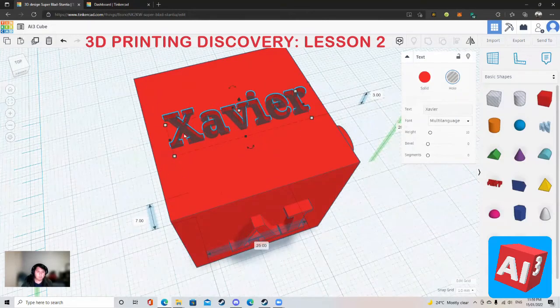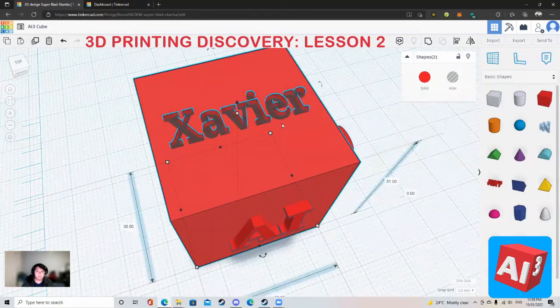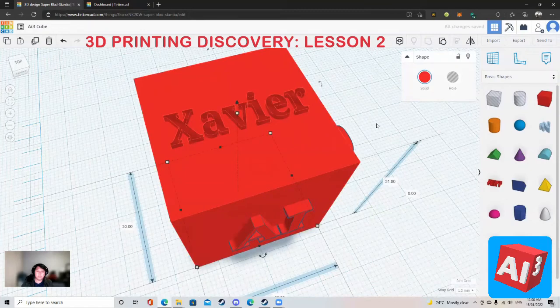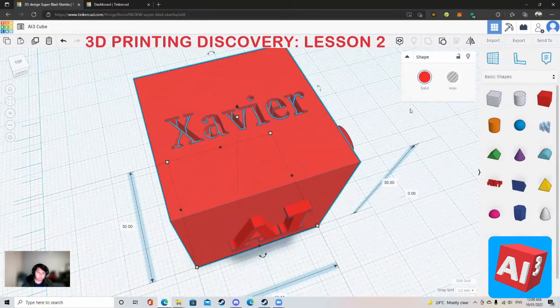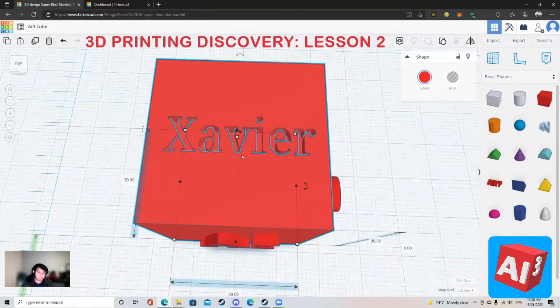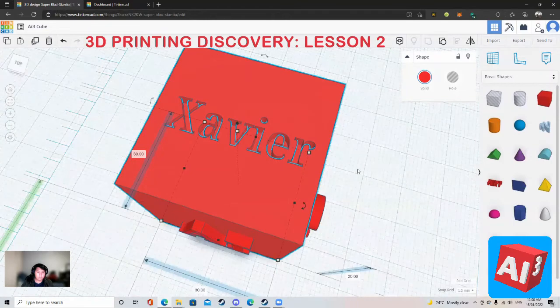So what I'm going to do is, while selecting this, I'm going to press Shift, select the other box, the other shape basically, and then I'm going to group them. Now this is one of the Boolean functions, and wait for a while, and you will see there we go. You will see your name carved inside the box like this, and voila, we're done.